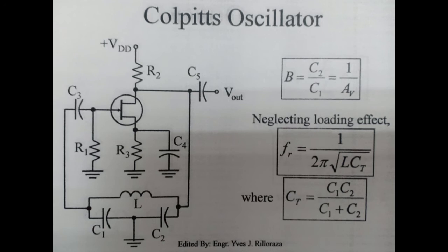The advantage of this type of capacitive circuit configuration is that with less self and mutual inductance within the tank circuit, the frequency stability of the oscillator is improved along with a more simple design. This is because the capacitors provide a low reactance path for the high frequency signal, and thus the output signal in the high frequency domain will be more sinusoidal.